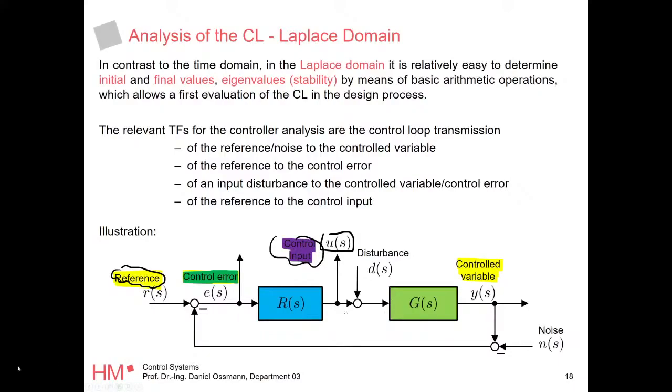Think of this car example, or think of an aircraft, which is probably a better example. If you have a maximum thrust of, I don't know, 50 or 100 kilonewtons, and you plug in the pilot commands and the control input gets to 200 kilonewtons, you will have a problem, because you have a hard limitation: your engine cannot reach that.